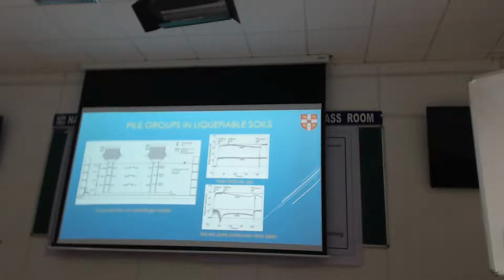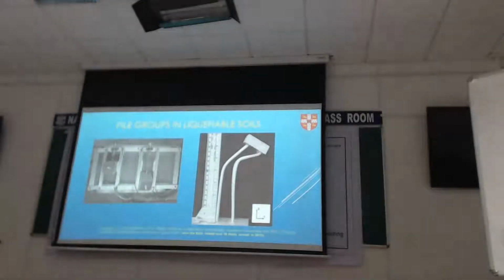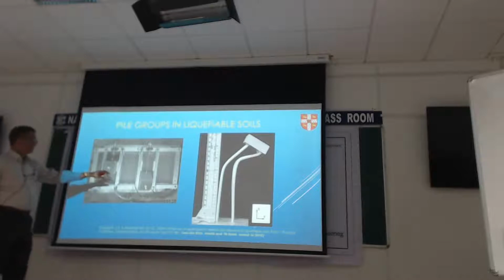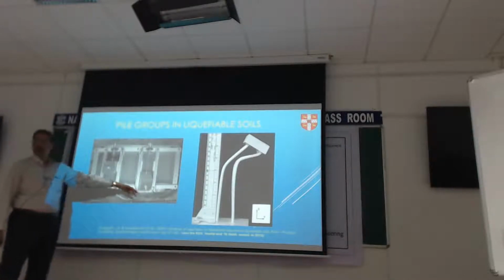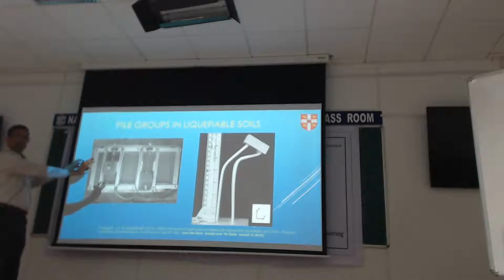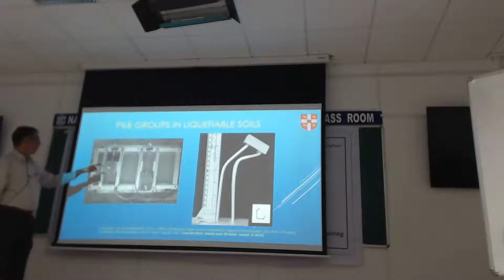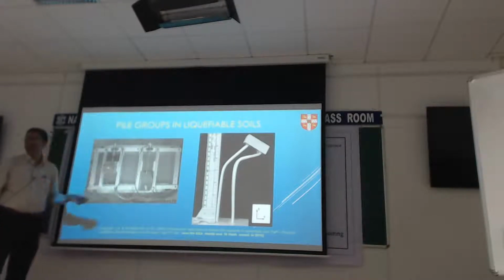So that's how we got rid of the inertial effects. Otherwise, every time we do this test, the piles will simply break under inertial load. Let me show you the picture, then I can come back. If you see here, a lightly loaded one deformed a bit and stopped, and the more heavily loaded one completely fell off. We are looking in plan view, and the shaking is in this direction, and these are allowed to go whichever way. We are able to measure the displacements and accelerations as well.